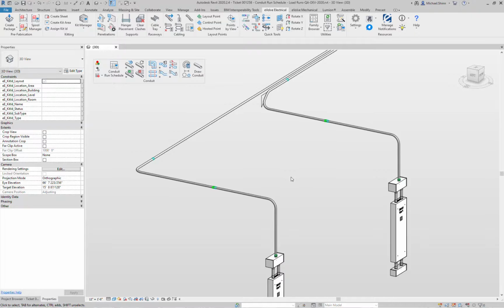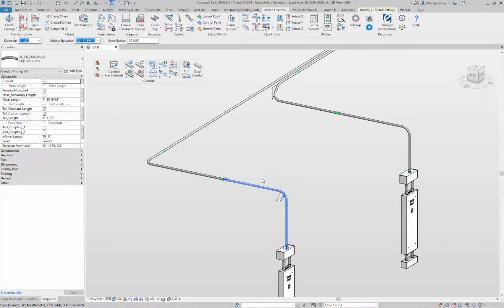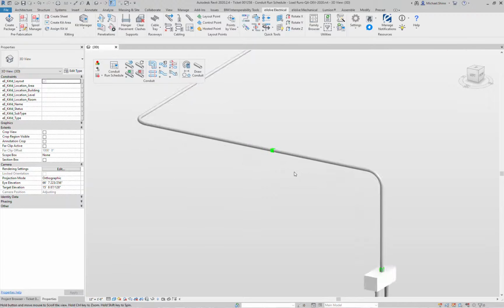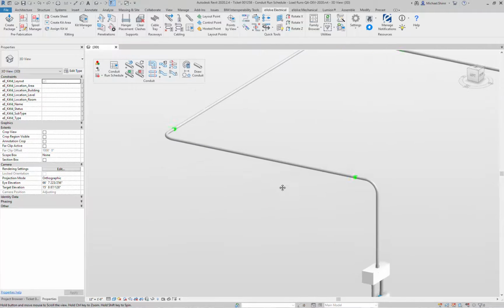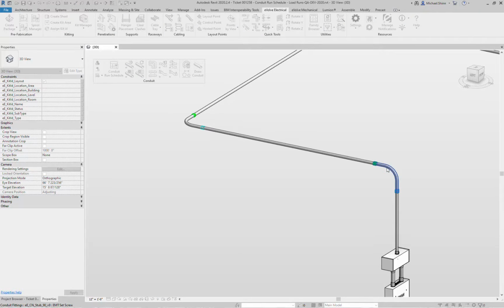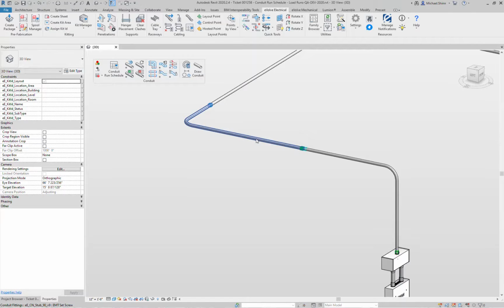So now what our tool has just done is, one by one, clicked onto each one of those bend families, and it has extended the tail and the nose. I'll click undo on that again for you. Hold down shift, which puts it into a single selection. I can click onto this bend, and it's going to basically turn it into a full 10-foot stick. Same thing here, turn that into a 10-foot stick. It notices that this is the shortest piece that it had available, so it extended that nose piece